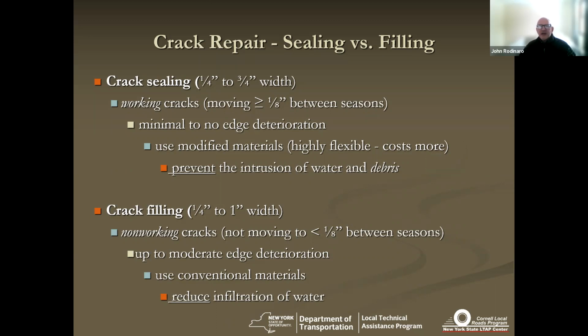don't want to be touching the crack once it gets, you want a minimum of 1/4 of an inch, otherwise you can't get material in there, but you don't want it any greater than 3/4 of an inch. That'll be too wide to really effectively seal. You want minimal to no edge deterioration, because you really want to give a good clean surface for that material